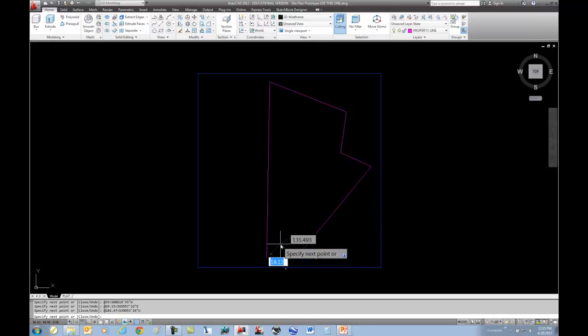In a civil drawing, whatever you're creating, you want to draw what's provided to you. Like if you're recreating this drawing, you don't want to snap to the endpoint because sometimes there may be errors in the drawing and it's not our job to fix it. It sounds kind of weird, but if you modify what's there without going out yourself and surveying, then you've just created something that doesn't reflect what is the actual recorded document. So in our purpose of recreating a recorded document, we recreate exactly what they have.